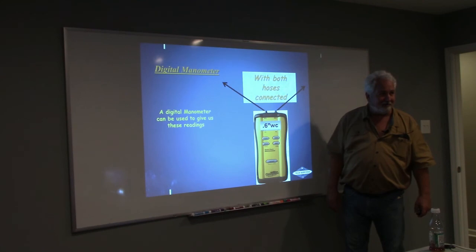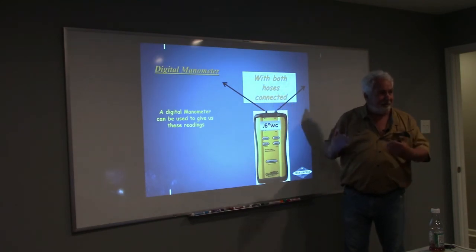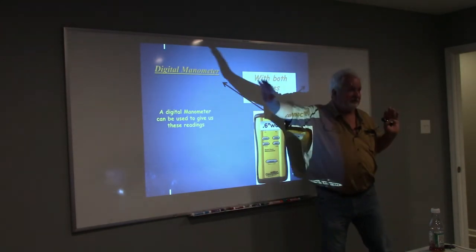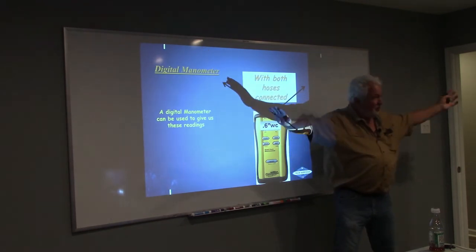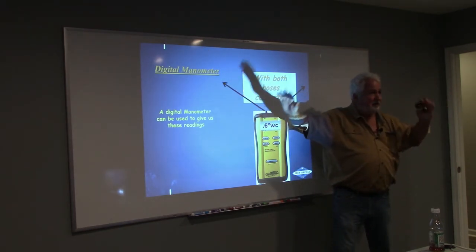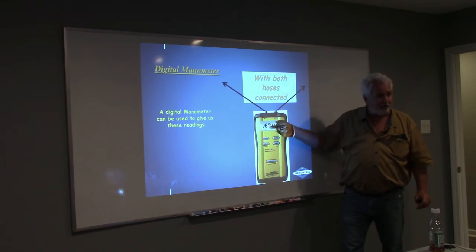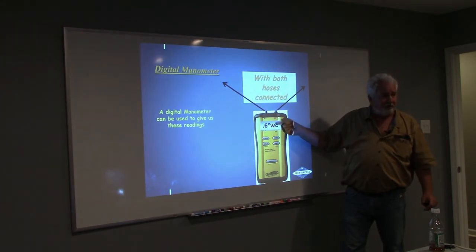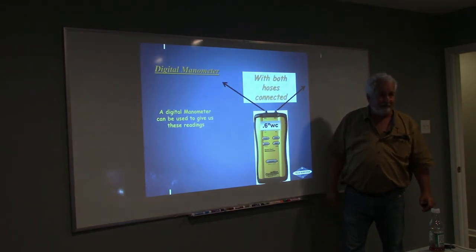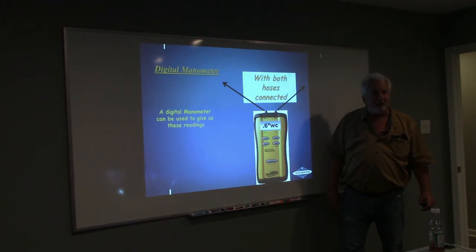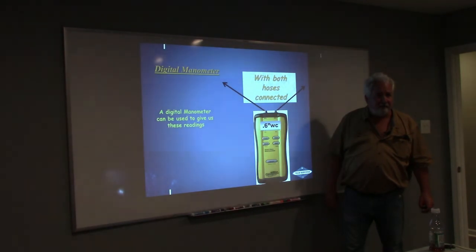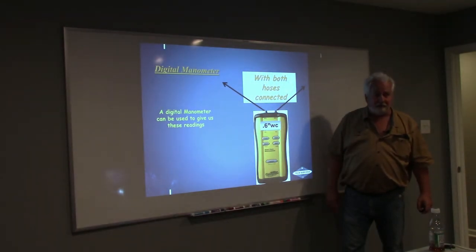0.6 inches of water column. The combination of the total of all the resistances I have to blow through and all the resistances I have to suck through. Those two give me the external static pressure of what that blower is really seeing. What that blower has to blow against: all the ductwork, all the grills, all the kinks, all the fittings, all of that, the filters.